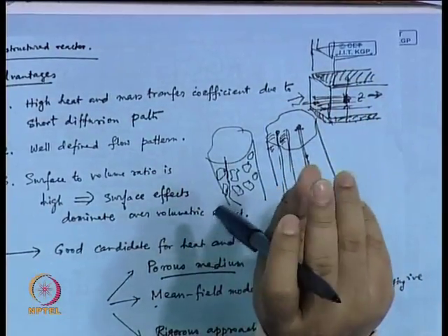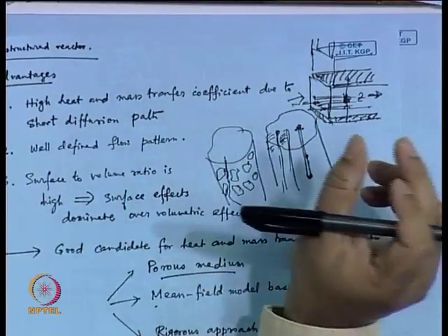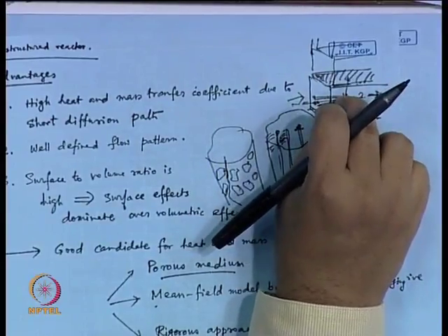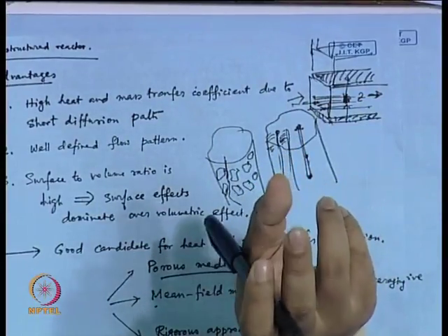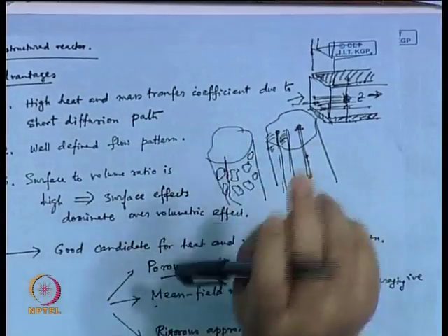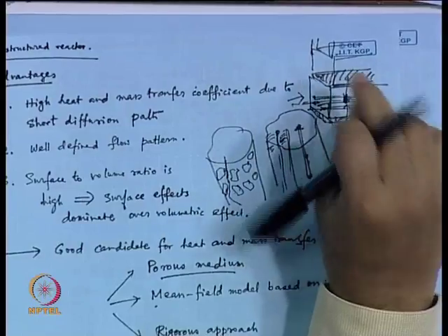Now, you have that window you are creating, and so you are producing side reactions, you are getting into other things. Now, the reason you are choosing a microstructured reactor is that this temperature delta T you can minimize. When we are talking about 1000, we are talking about 995 to 1005. That window is going to be smaller in a microstructured reactor.